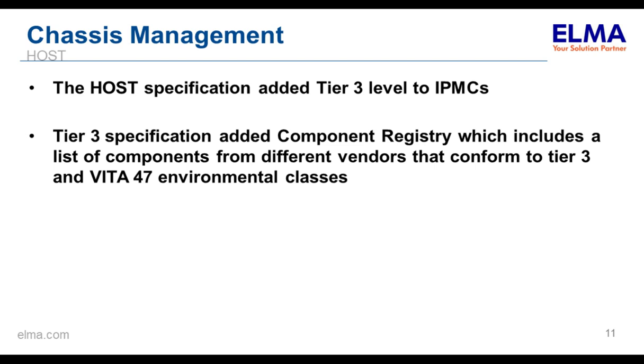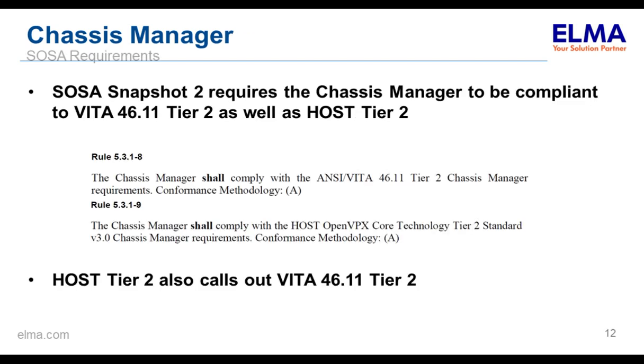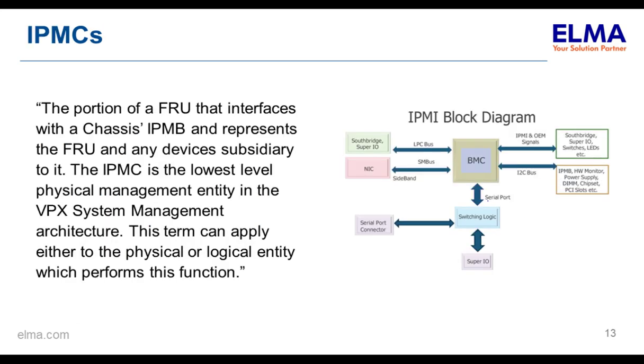However, SOSA and VITA 46.11 do not have the Tier 3, at least at the moment. So as I mentioned, SOSA Snapshot 2 requires the chassis manager to be compliant to VITA 46.11 Tier 2 and HOST Tier 2. And HOST Tier 2 also calls out the VITA 46.11 chassis manager.